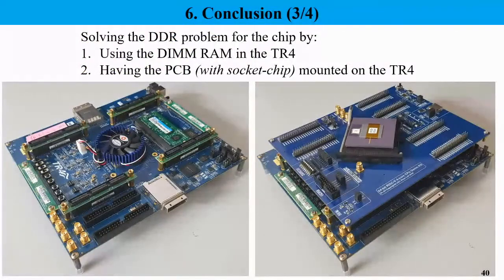This photo shows the TE hardware demo, interfacing the chip with the FPGA for the DDR controller. Both of the chips do not actually have a DDR controller built inside, so we decided to externalize the main memory, the main memory tiling port, and with this we connect the PCB to a tiling port inside of the FPGA, which contains the DDR controller.